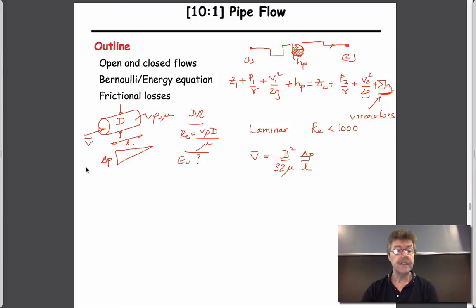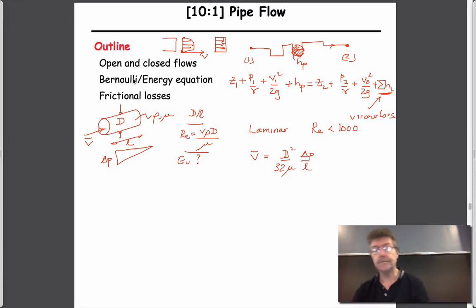And so this average velocity, you'll remember, I can't really get it in here, but let me draw it here: if you're looking at the outlet of the pipe, the true velocity profile is this kind of parabolic profile with zero velocities at top and bottom. And what we're doing is assuming that it looks like this, where the area under the curve of each of these figures, this parabolic figure and this prism, are the same. So the product of velocity times area, length across the pipe, is the same.